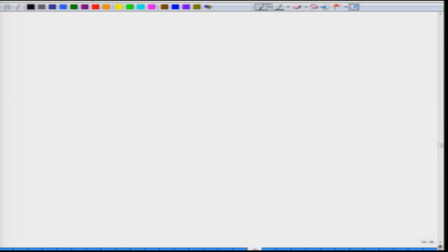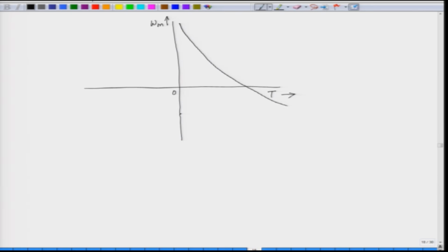Now, if you see the speed torque characteristic of a series motor, we have speed in the y axis and torque in the x axis. This is how we plot the speed torque characteristic, and for the reverse motoring, this is our speed torque characteristic.